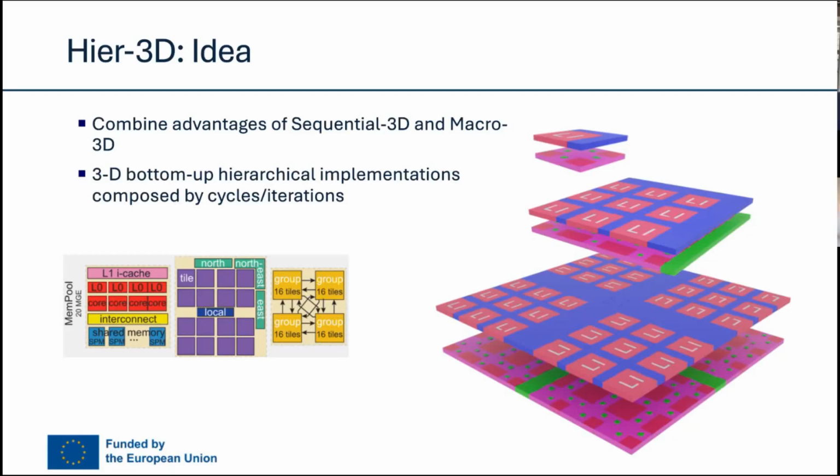In the next iteration, we just connect the different groups together, and now our flow is fundamentally similar to Macro-3D, where again, we are just placing the standard cells in the bottom tier in the regions which are in green. Notice that when we are in this step, there are some areas that we reserved already in the tile with green areas that can be reused right now. This allows a great flexibility in terms of the location of the buffers when we are generating the complete system.